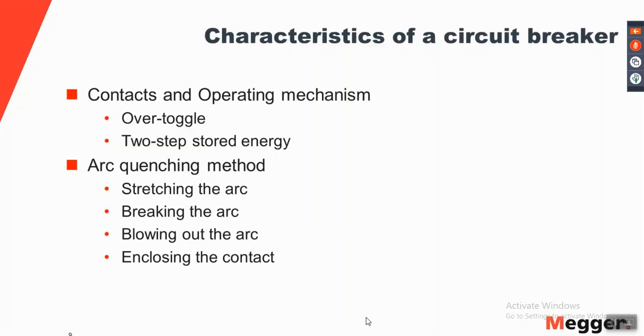Then there is the two-step stored energy mechanism, which is used in low voltage power circuit breakers, where there are separate springs for opening and closing of the breaker. So you can actually charge the spring for closing a breaker even before it has opened. What that does is give a reclosing ability to the breaker. So if the breaker opens in the case of fault, it can be immediately reclosed remotely.